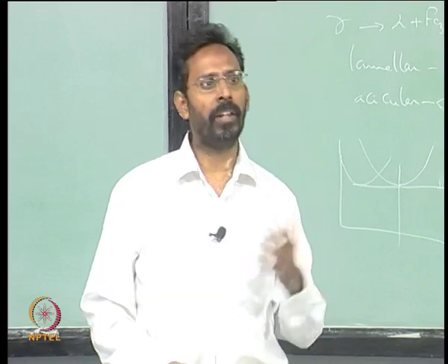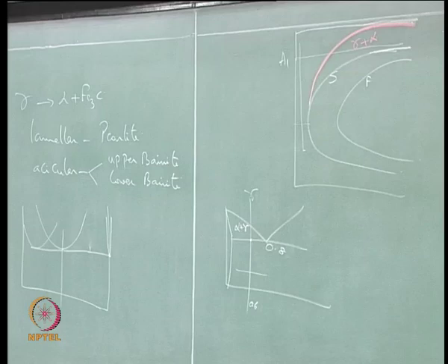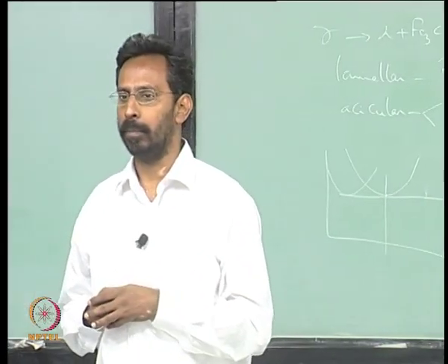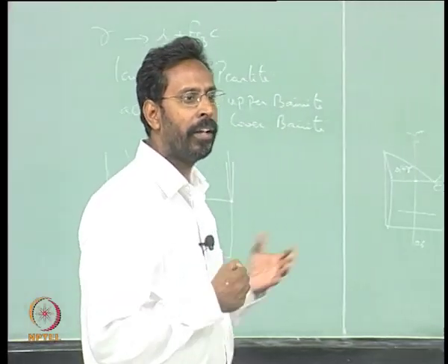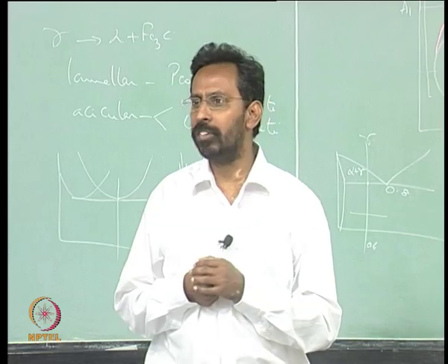Normalized sample. Anything more? The interlamellar spacing within the pearlite is coarser in the annealed sample and finer in the normalized sample. Why? Because the nucleation rate is higher. Why is the nucleation rate higher in a normalized steel?